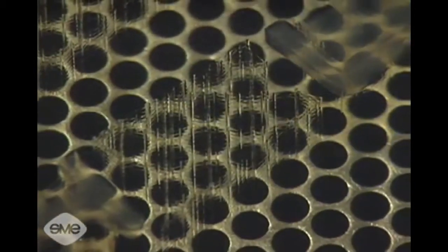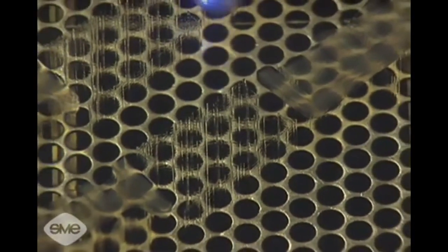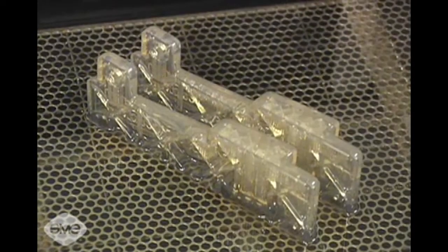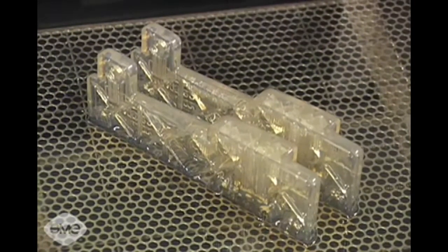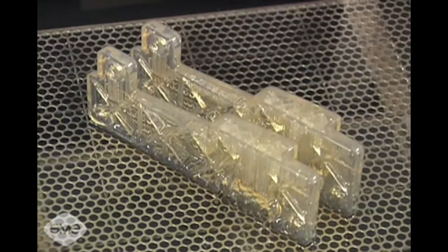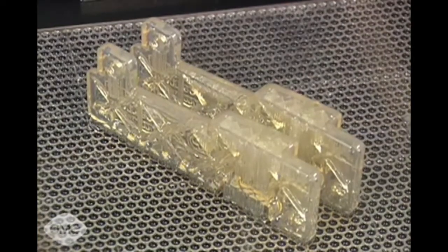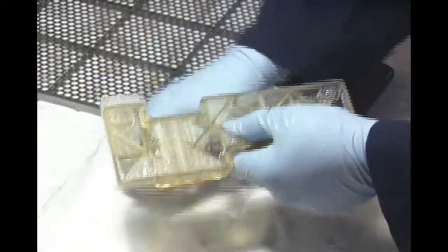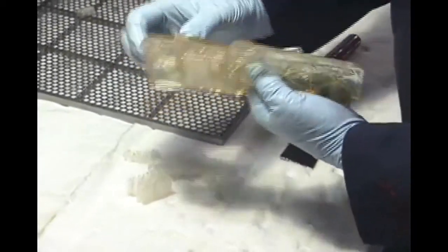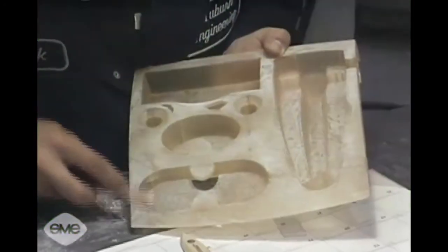Minimum layer or slice thickness ranges from 1/1000th of an inch to 12/1000ths of an inch. Supporting ribs for overhangs and undercuts are built up along with the model and later removed by secondary operations. When the model is complete, the platform rises out of the polymer reservoir. Once the excess polymer drains away, the model is removed for post-processing, such as removal of supports, additional curing, and surface finishing.